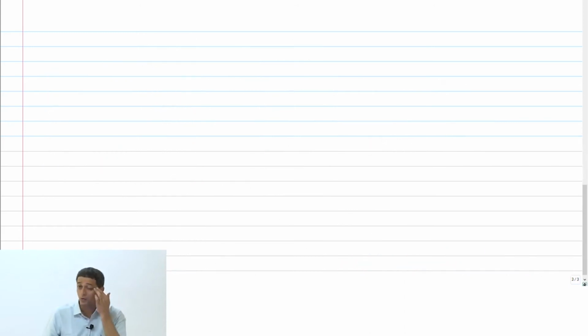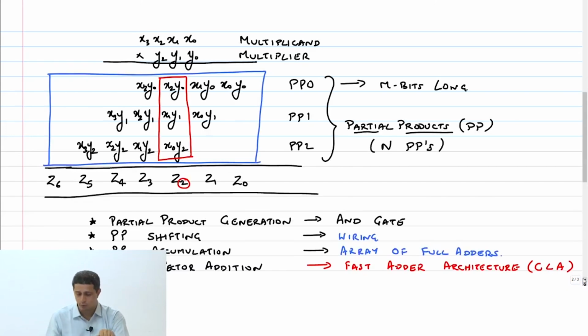Okay. Now what we discussed was only for unsigned numbers. We will come to it when I show you the implementation using full adders. You will find that there is one final addition that needs to be done. You put these arrays together, put enough number of full adders. Suppose you are doing 4 cross 4 multiplication, you put 16 full adders so that you can do this multiplication addition appropriately.